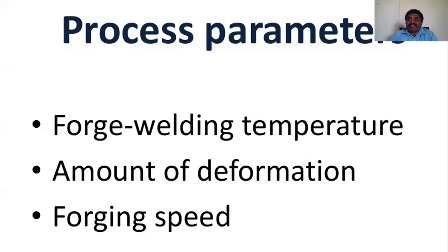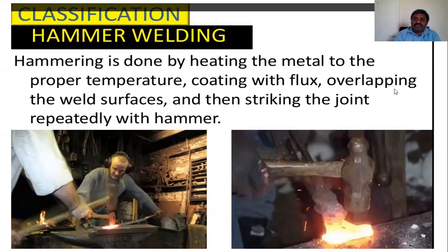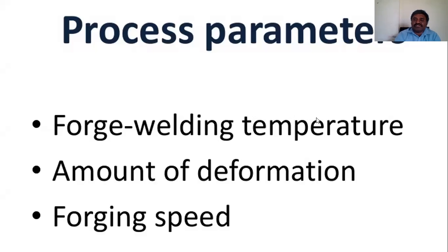If only one person carries out the forging, as you can see from the previous diagram, and the speed is not maintained, the metal easily solidifies and it becomes very difficult to get a joint. So we also have to take care of the forging speed.